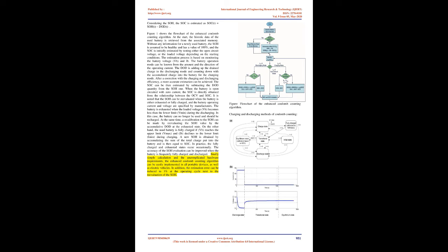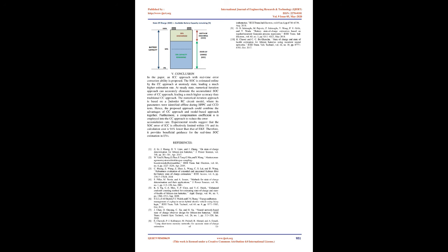When a battery is discharging, the depth of discharge, DOD, can be expressed as the percentage of the capacity that has been discharged relative to Q_rated. Q_released is the capacity discharged by any amount of current. With a measured charging and discharging current, IB, the difference of the DOD in an operating period, T, can be calculated by where IB is positive for charging and negative for discharging. As time elapsed, the DOD is accumulated.